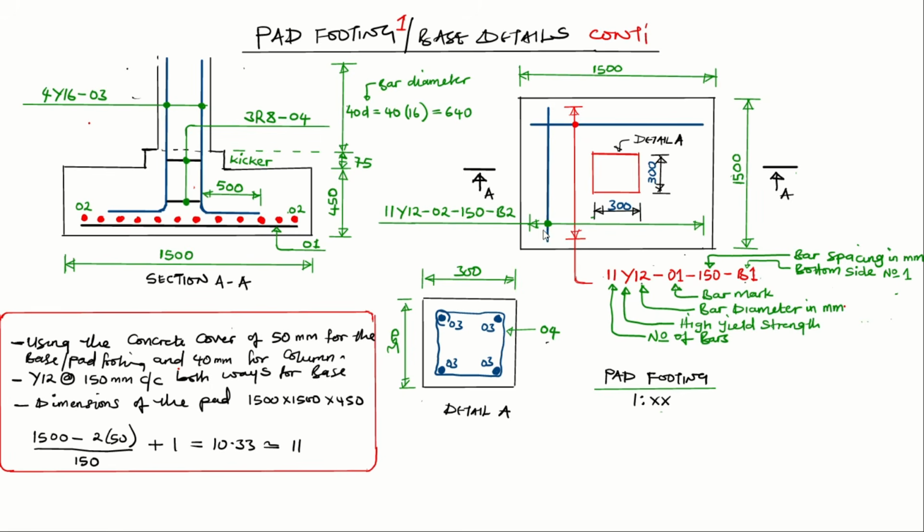So now, you also need to give a name to this reinforcement. Now, the name, how do you give it? Remember that you have to do the calculation of your what? The number of bars. So now, to calculate the number of bars, this one is being distributed in this direction. You're going to get the length that is in this span from left to right. And that direction is what? This here, which is 1500 millimeters.